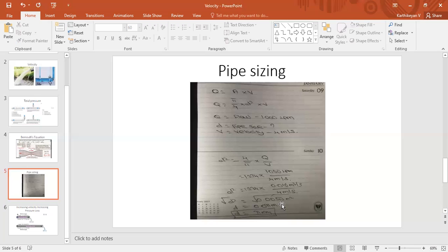What I'm trying to convey here is, if you feel your source pressure is too high and you want to adjust or correct the pressure, you will adjust the pipe size. If you adjust the pipe size, the velocity will automatically come to a normal number, so it will not go too high. So this is the reason NFPA 13 does not restrict the velocity of fire water.